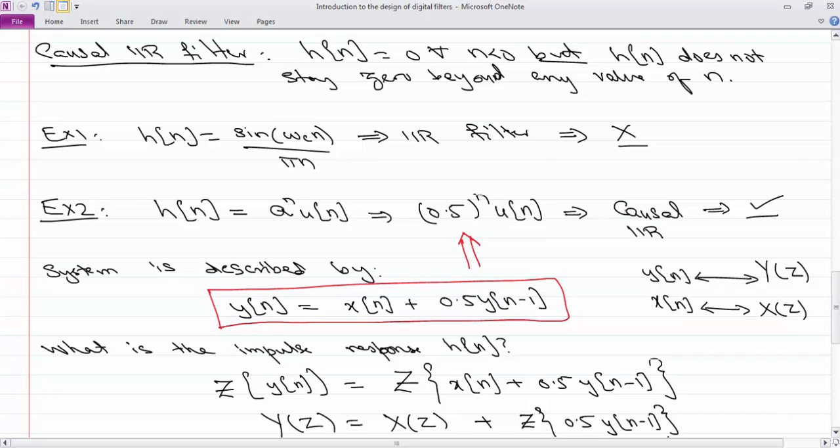So writing this code is really simple. Even though your impulse response is infinite, you can implement that because it is given in terms of a difference equation. You're not going to use the convolution formula, but you can implement it in terms of a difference equation.